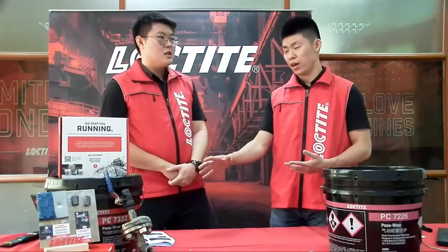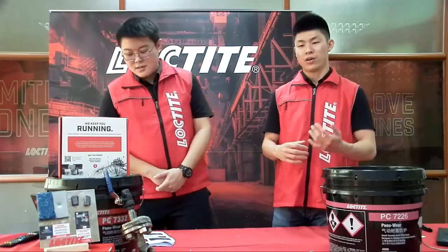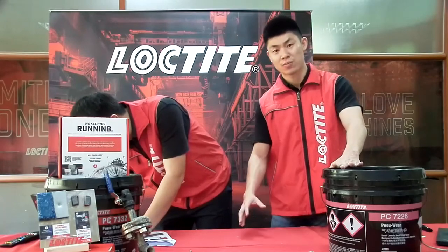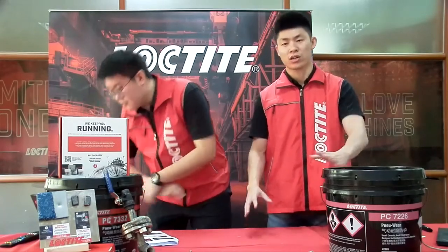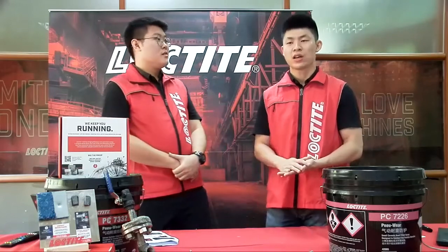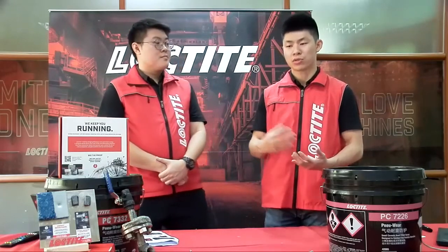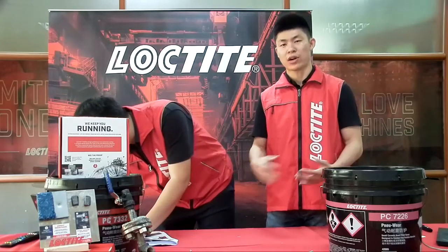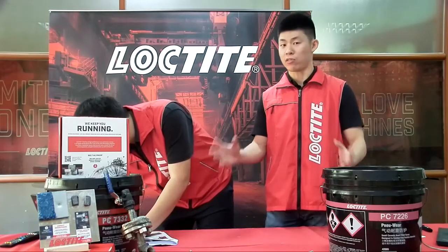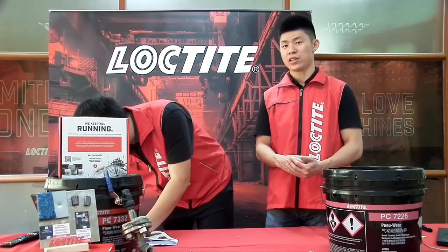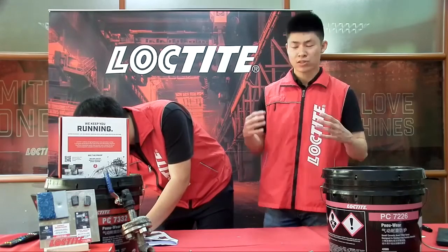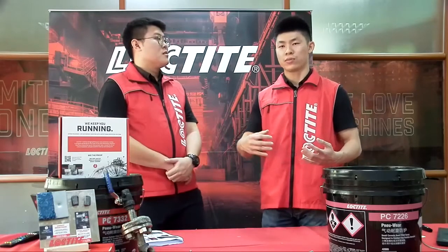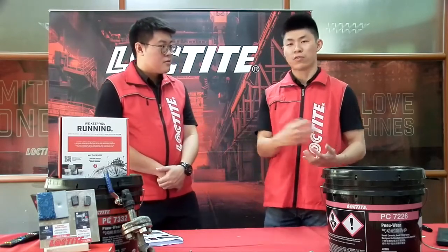But like what we always mention, for those products, if you are applying on very dirty metals or unprepared, unclean surfaces, the first recommendation I will give is make sure the surface is cleaned. You can clean it using power tools like a grinder, or you can sandblast if you have the luxury to do that. If not, you can use sandpaper. Just make sure that you remove the loose rust on the metals before you apply